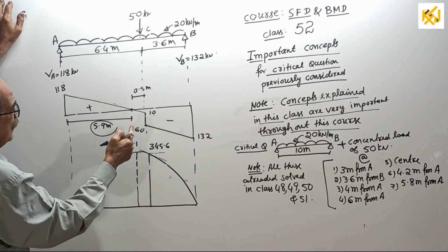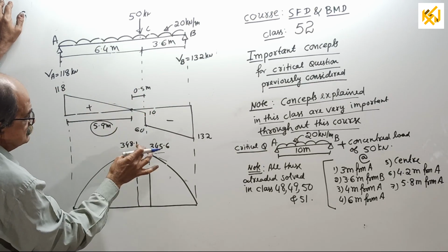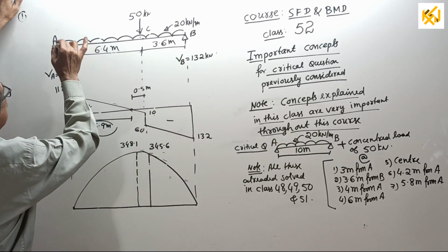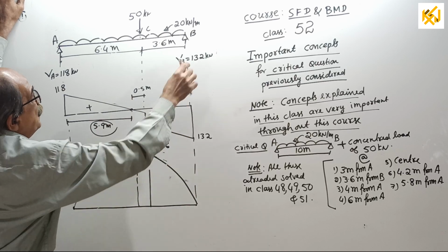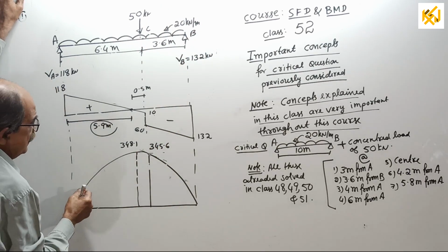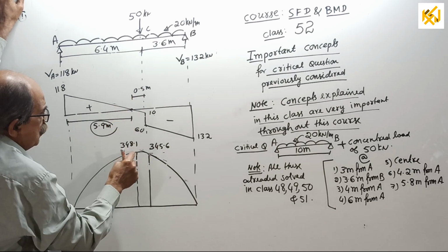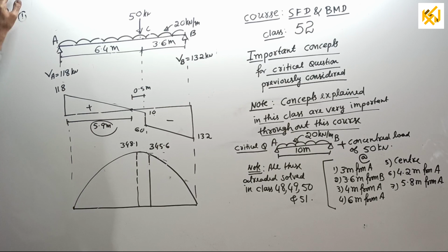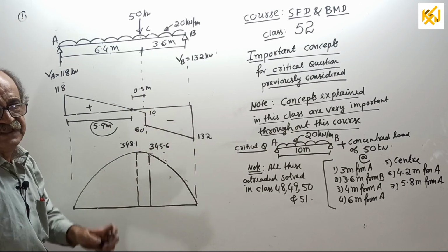How much should it be? Only 10. Okay. Now, see, 0 bending moment here, it increases parabolically, directly increases here. Here it increases, reaches the peak value, then again drops down. This is the bending moment diagram for the second example.